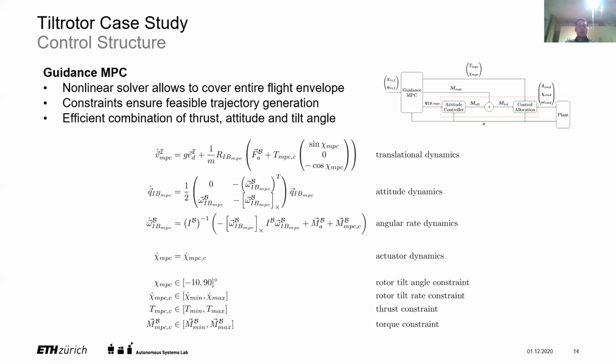Now, after the MPC, as we saw, we have this fast inner loop. First of all, the attitude controller. I will not say too much about this since the setup is fairly trivial, but again, the idea is that the attitude controller helps to improve the overall stability. As you can see here, the MPC problem is still rather high dimensional, and it is also nonlinear.